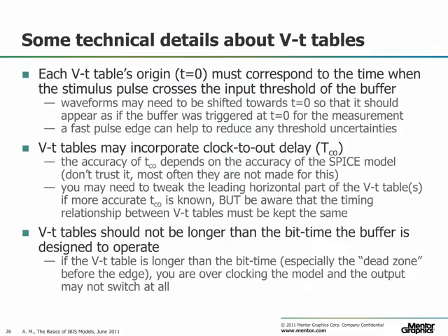This depends on how much detail of the pre-driver circuitry is included in the transistor models from which you are generating this waveform. Since the first and last points in a VT table correspond to the buffer being in the steady-state conditions, you also have to make sure that the slopes at the beginning and the end of the VT table are horizontal. Since IBIS models do not support overclocking, you also have to make sure that the length of the VT tables are not longer than the bit time for which the buffer was designed to operate.